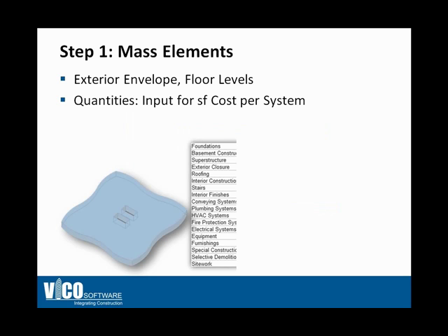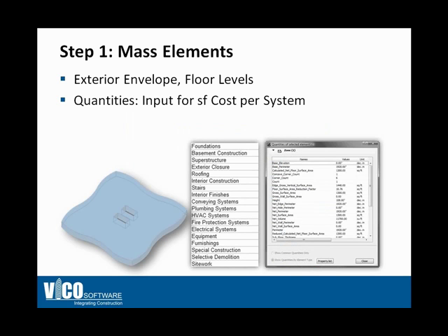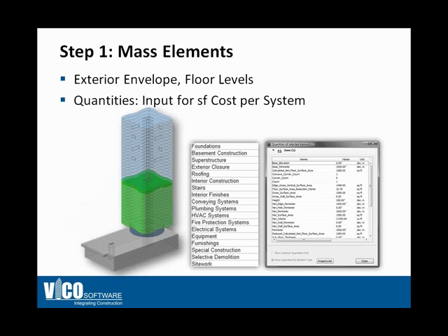The first step is going to be a very conceptual phase of the project, where we only have an outline of the building, basically the building envelope, and we know what the floor levels are. By stacking those floor levels, we can create a schematic or very, very simple representation of the plans that we have for the project. The square footage that we can get out of this type of geometry will help us to do a cost calculation based on square footages for each of the systems that needs to be included in all of the spaces that we've identified.